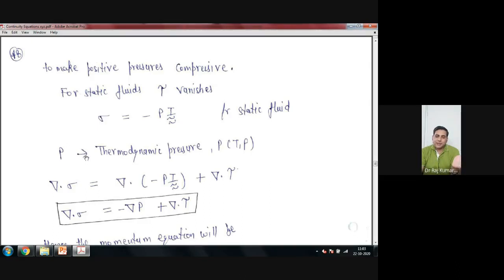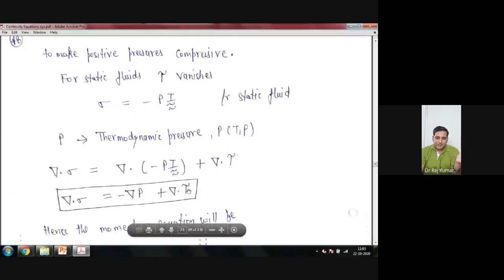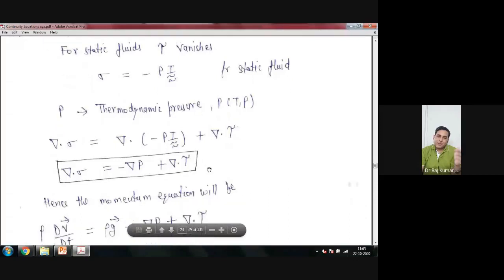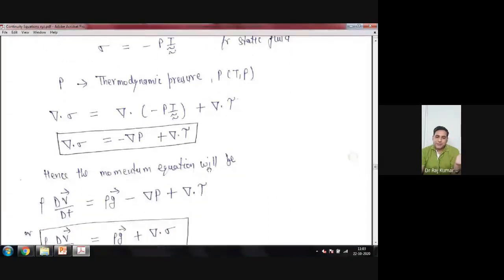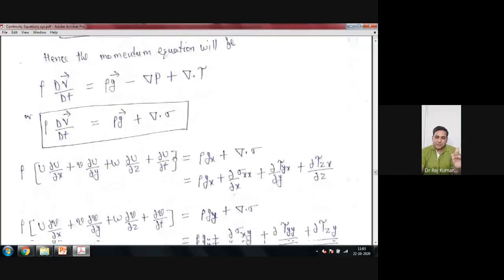So you are putting del dot here, the sigma. So you just put del here also. In the previous slide you have a tau. You have also put here del dot tau again. So you got del sigma equal to del p plus del dot tau. So finally, you can change your continuity equations this way, that your force balance equals rho dv upon dt. So this is another way to represent your momentum balance. So I will end the momentum balance on the x plane here.